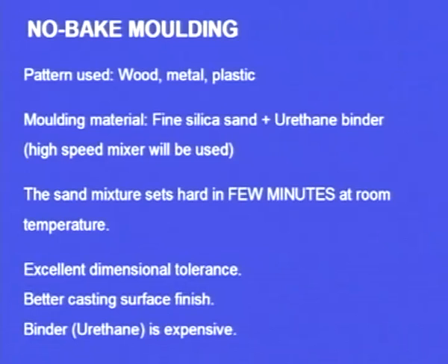We do not have to pass carbon dioxide, we do not have to bake it, within a few minutes it will be hardened. So, this is the advantage and the special feature of the no-bake moulding system, and it offers excellent dimensional tolerance.